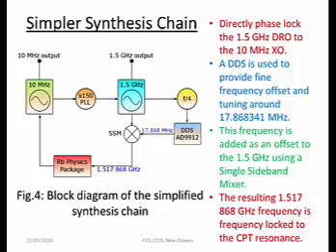Then we could possibly use a DDS, which could be clocked by dividing down the frequency from the DRO. That would produce a 17.8 megahertz signal, which we can tune and modulate directly from the DDS. Then we can offset the 1.5 gigahertz frequency using a single sideband mixer, and that will produce the frequency to interrogate the rubidium-85 resonance.